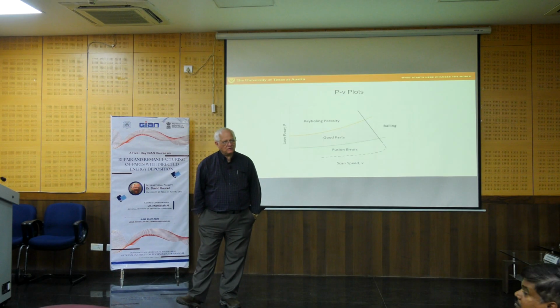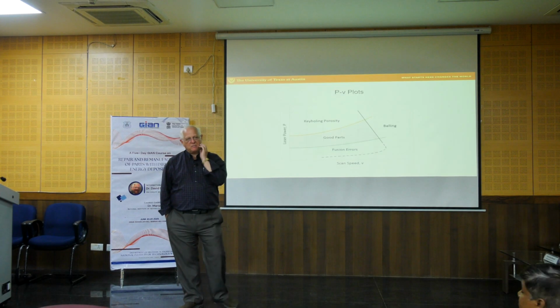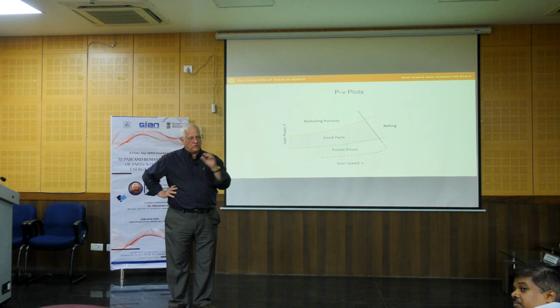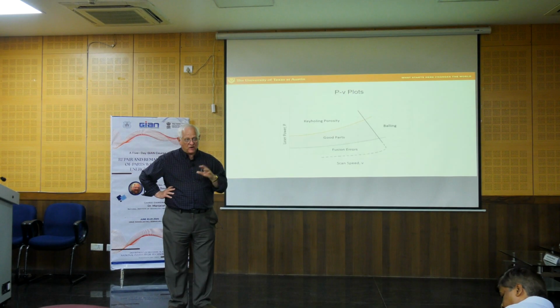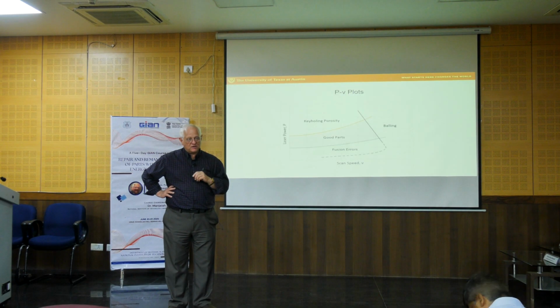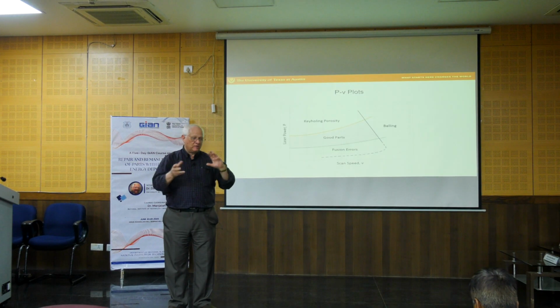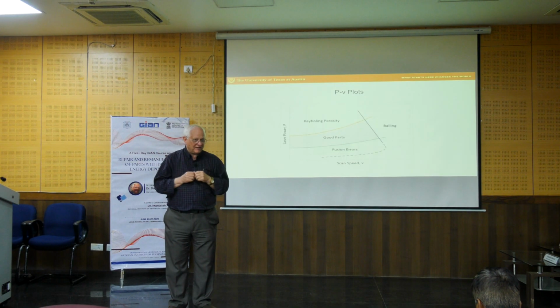Right. Sure. Functionally graded materials is a very interesting area, and it turns out that of all the processes for additive manufacturing, direct energy deposition is the one that's best suited for producing multiple materials. Because we can simply have multiple powder jets of different materials, and you just turn them on and off depending on where the scan is, and you can create these parts.